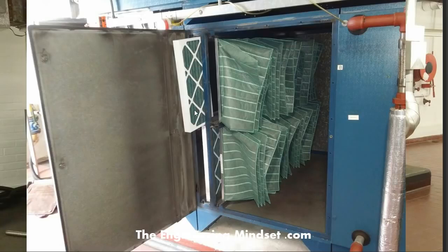In this example, you've got the panel filters almost directly coupled to the bag filters there. And if you imagine the air is coming through, these really kind of inflate as they add resistance to the flow of air, and these will start to clean and capture all the dirt out of the air, which we saw earlier. And here's one of the bag filters we just got out of one of the boxes, just to show you the sort of material it's made out of and its construction. You see these bags going back to capture all that air.